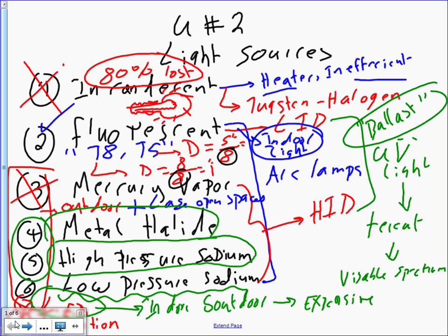Can I emphasize one thing, guys? After you put the fixture in, do you expect the same amount of lumens? There are chemicals in it. The longer it takes, two things are going to happen: the lumens are going to go down, and the fixture is going to die on you. How long it takes for the fixture to die, and how many lumens you lose, will decide how good a fixture you have. That's when you start specifying the fixture.